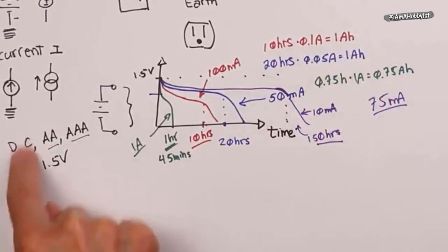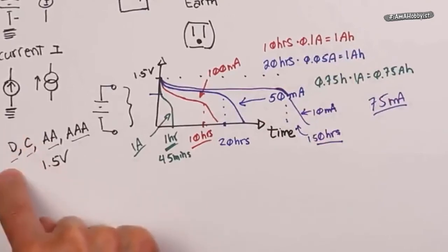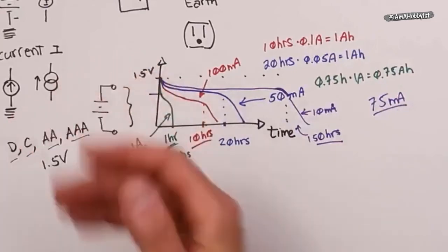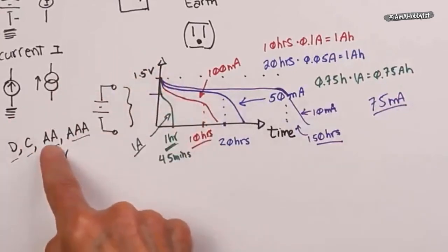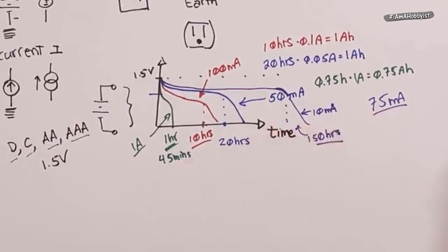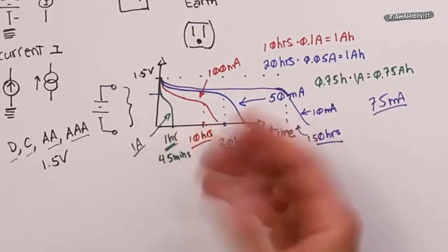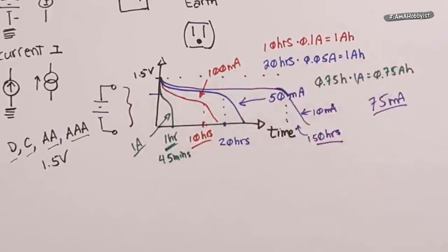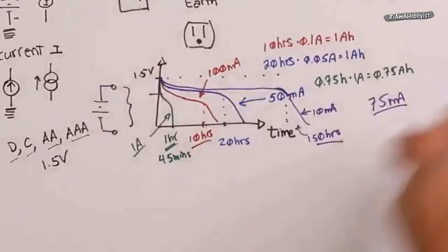Over here on a D cell, we're talking a few amp hours. Depending on the chemistry of the battery, you might be talking 5, 8 amp hours. You get down to AAs, and you might be talking 800 milliamp hours, 500 milliamp hours. It's just physically smaller. Even if it's the same chemistry, it doesn't have as much energy capacity. Okay?